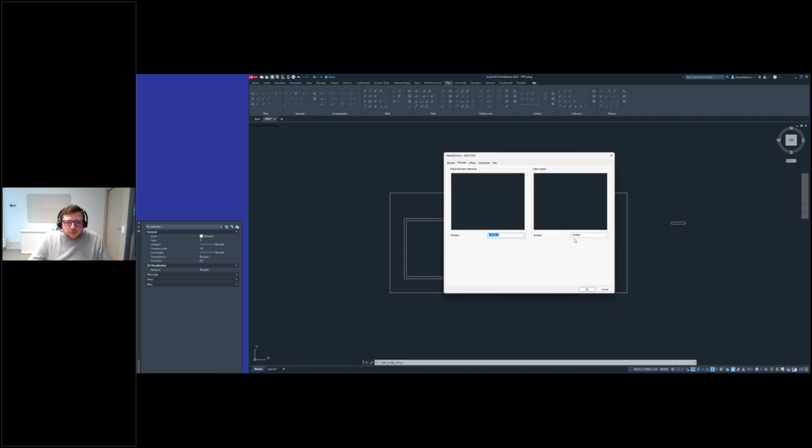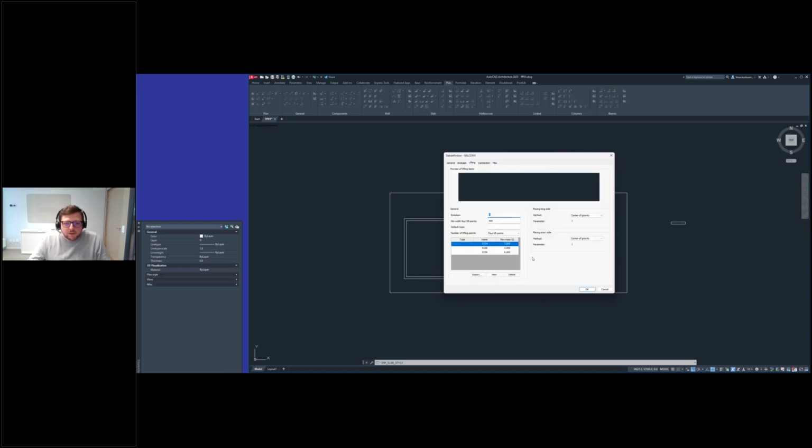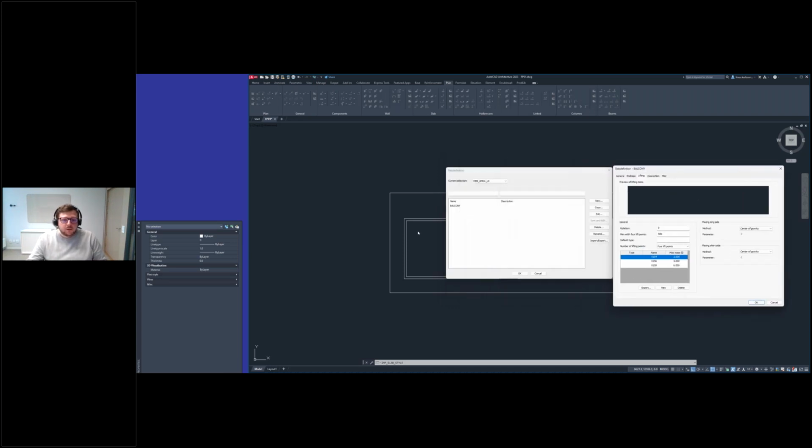In the end caps, I want to control them for each individual case, so I left that open. I have the configuration of 4 and 2 lift points, and 4 lift points is the top of the slab, and 2 lift points is what we're going to use here.